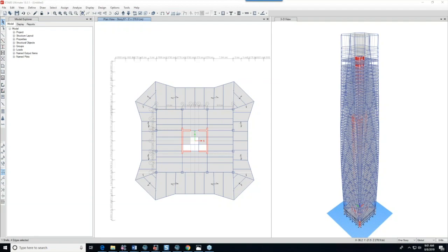So today we're going to be talking about rigid and semi-rigid diaphragms. And I really believe that this is one of the things that you have to put on your checklist when you're creating an analytical model. You really have to ask yourself, how am I going to treat the floor diaphragms? And there are times when it's completely appropriate and desirable to treat the diaphragms as rigid.